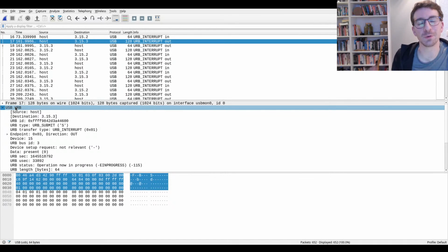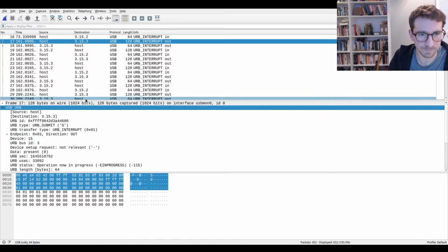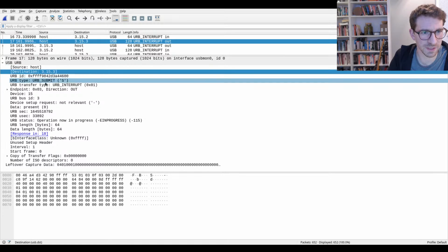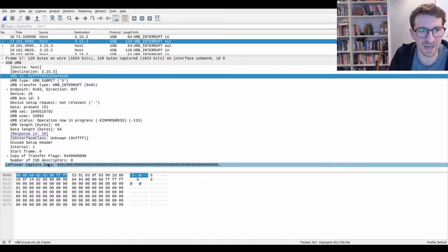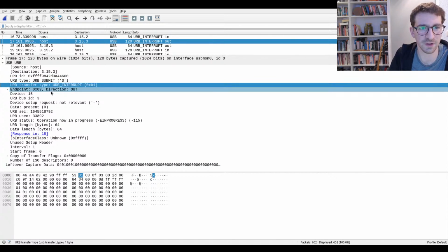Yeah, there's all this physical layer stuff that happens, but in this case, we're just seeing the high level view, quote unquote, of what the kernel thinks of USB traffic happening. So what we see here, let's make this a bit bigger, is that there is a source and a host and everything, and then there's an ID. There is basically a transaction ID at the top of the packet, and then there is a type, and then there is a transfer type.